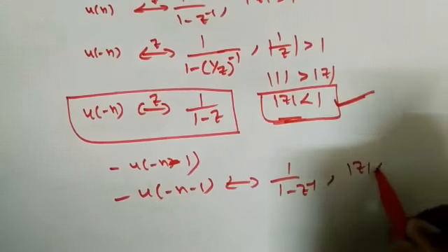Now what is the z transform of this type of signal? x of n has X of z and ROC is R. Now if we do the expansion, that is x k of n, in the z domain it will become z power k, right? So z power k means, suppose what is the z transform formula? X of z is equal to sigma n equals minus infinity to infinity x of n into z power minus n. Now if I take z power k, what happens here? n equals minus infinity to infinity x of n into z power minus k power n. Yes or no? Now see, we will get only integer multiples of this one.